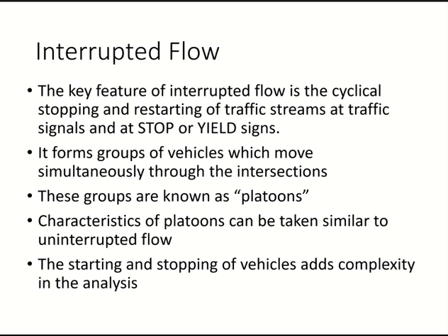Okay? So you have a group of vehicles, they are moving. You want to calculate their density, speed, capacity, whatever. You can use those equations, no problem. But when this group reaches the intersection or comes close to the intersection, you stop your equations. You stop your calculation. Clear? Okay? Why? Because on intersection we have, you stop. If it is clear, you will go, otherwise you will keep waiting and so on. Clear? Okay. But because of this thing, we cannot use those equations on the intersections.